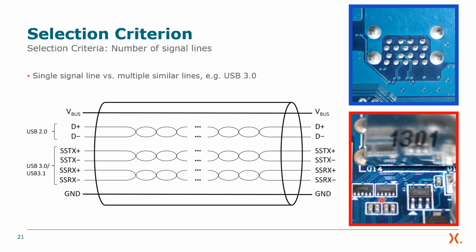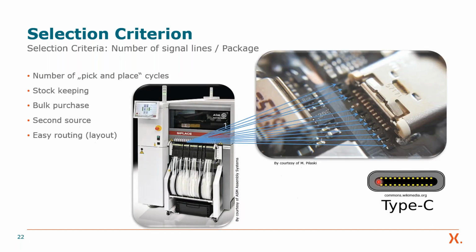However, in practice, and especially when it comes to high data rates, like in USB 3, this is actually not needed because the parasitic capacitance of the devices is so low that the relative deviation can be rather high. So you can also select single devices to protect every data line. This has some benefits, like shown here.